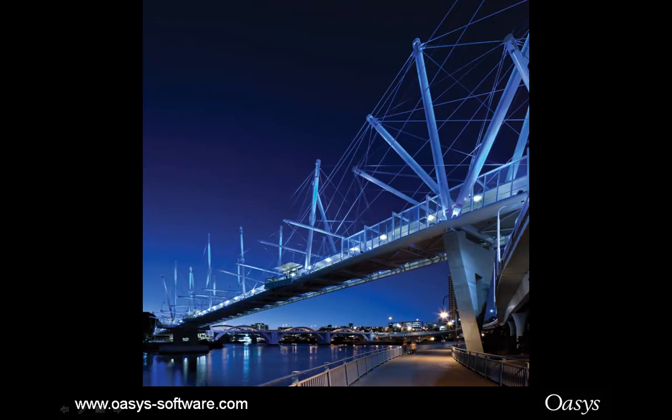Now, this pre-tensioning and form finding also becomes useful for other structures, such as this Kurilpa Bridge in Brisbane, which is a tensegrity inspired structure. This was built over a busy waterway, and the site constraints and the contract constraints meant that there was very little, if any, opportunity to adjust the cable lengths once they were in position. So the engineers had to work out the pre-stresses and the cable lengths up front using GSA, of course, and it all fitted together very, very nicely.